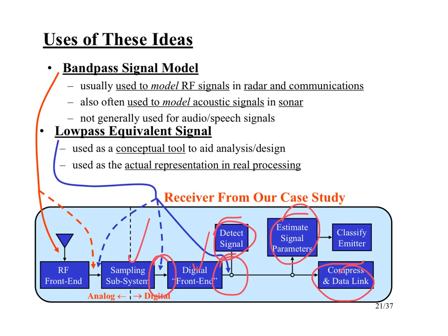Now, we might also convert at some point that IQ into envelope and phase. So, for example, when we're doing signal detection or maybe even classification of emitters, we might want to look at the envelope shape and the shape of the phase to see what kind of pulse shape we have, what kind of pulse widths we have, whether we have a linear FM modulation on our pulses, things like that.